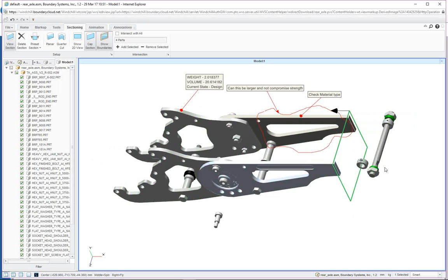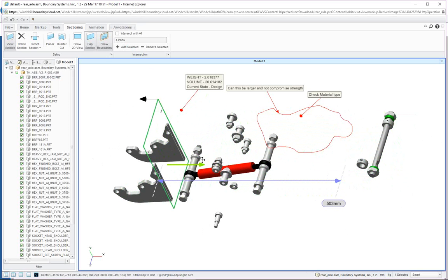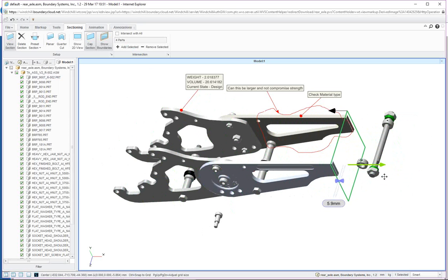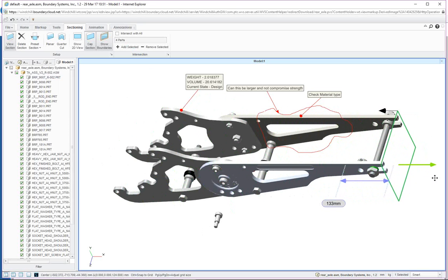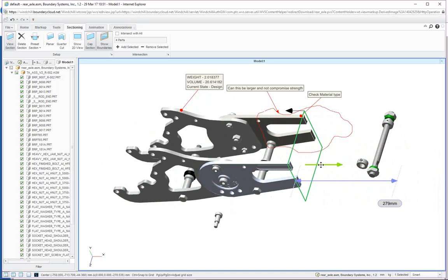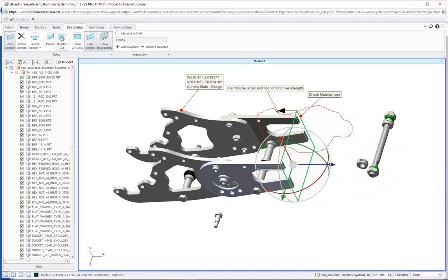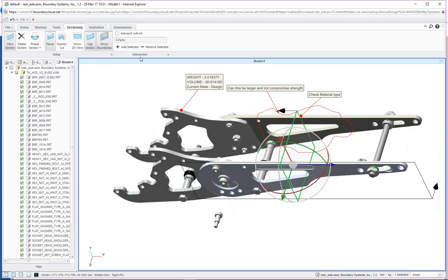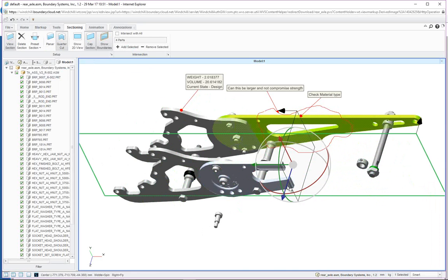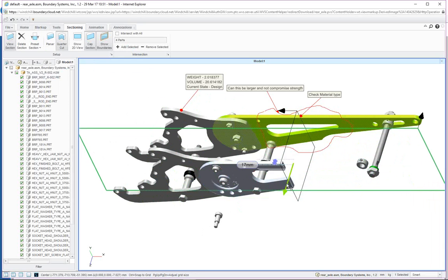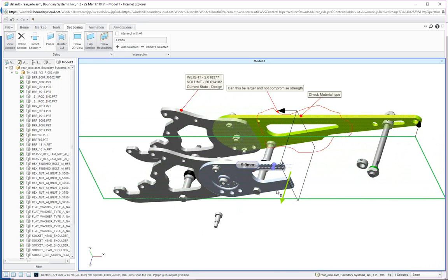So now as I drag my cross section, come on, there we go. Now as I drag my cross section, we can see just those specific items cutting, just like we can when we're inside of the actual 3D model inside of Creo. Now the other thing that we can do is specify a quarter cut as well. So we can then cut it in the second direction. There it is. And still use the drag handle to cut that as well.